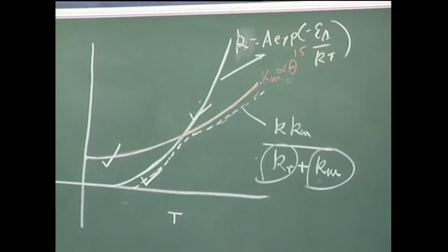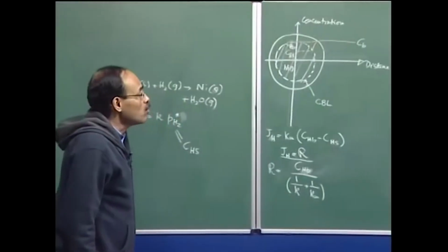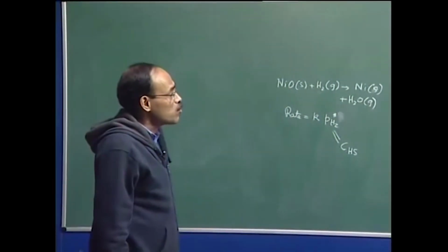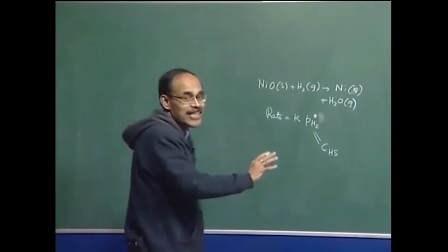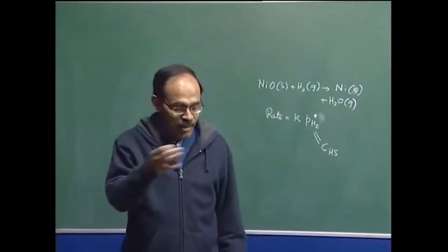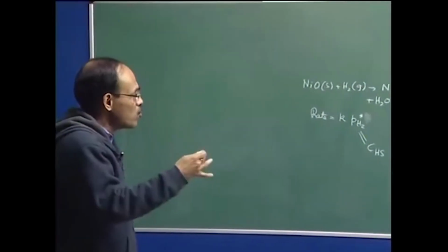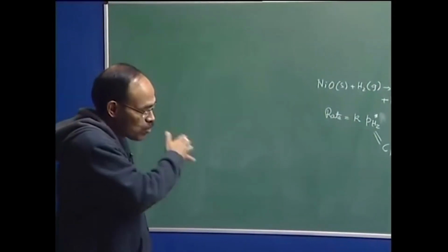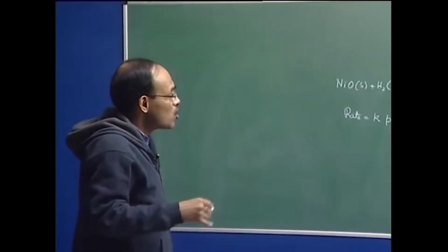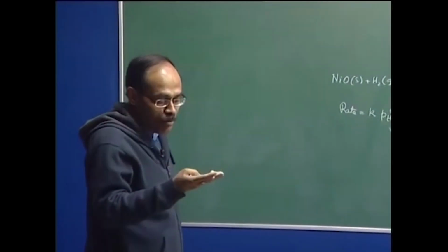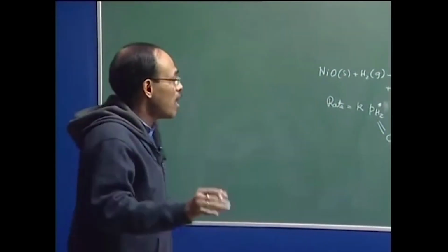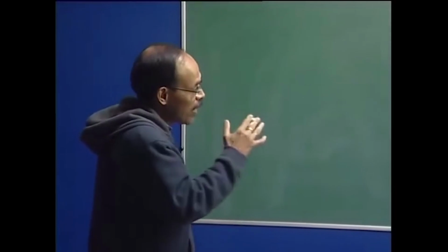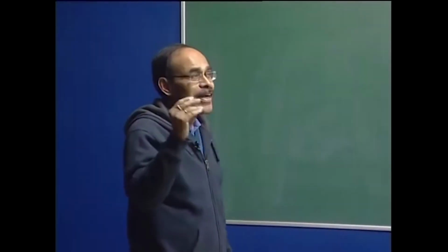So therefore, due to chemical reaction and due to mass transport, looking at the values of Km and Kr, we should be able to conclude whether mass transport is rate limiting or chemical reaction is rate limiting. Now the subject is endless, I can go on and on, but this is just to revise and remind you of the basic concepts as you go through the subject of steel making. All these things, starting from thermodynamics, fluid flow, heat transfer, mass transfer, chemical kinetics, are essential for us, and we have to have a good idea of all these subjects in order to handle steel making